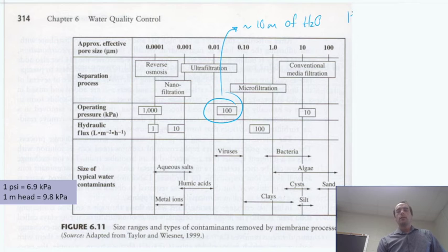I think it's GE made a membrane system called the Sky Hydrant, if I can spell. The Sky Hydrant is essentially an ultrafiltration membrane designed for use with elevated water sources for developing countries or maybe disaster relief scenarios where you have some way to elevate your water and use gravity to pressurize the membrane, and you have a system in place where you can change the orientation of the flows to do a backwash every now and then.